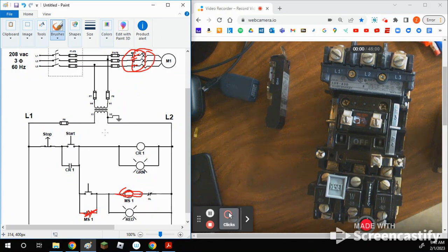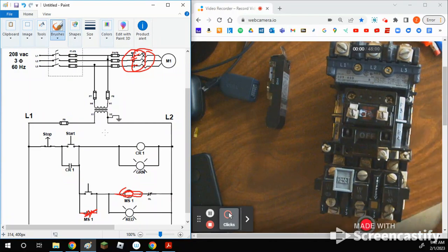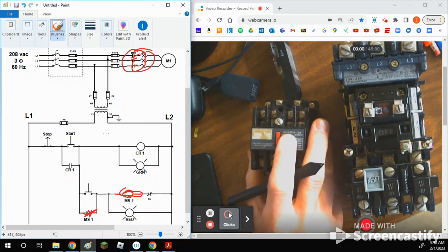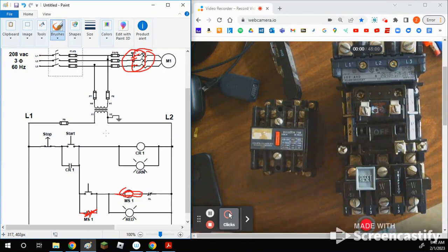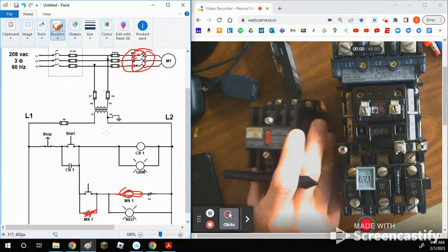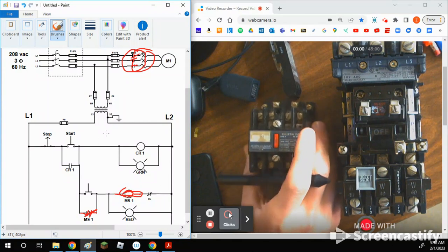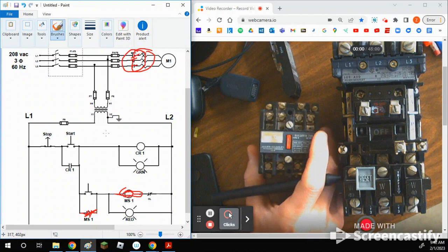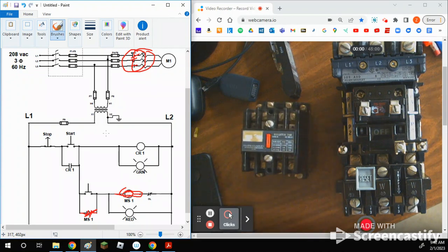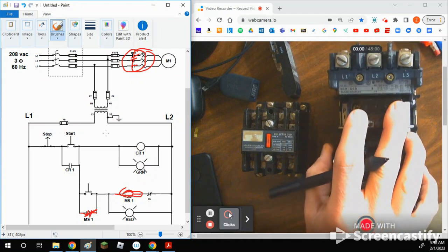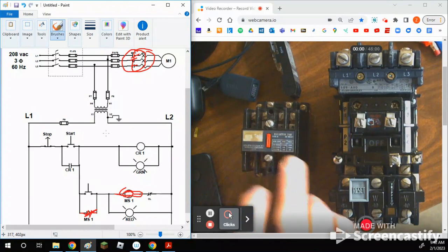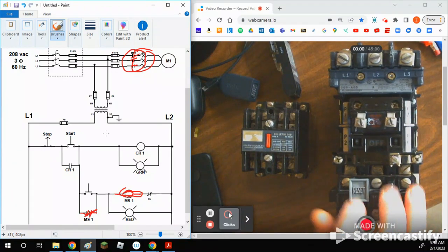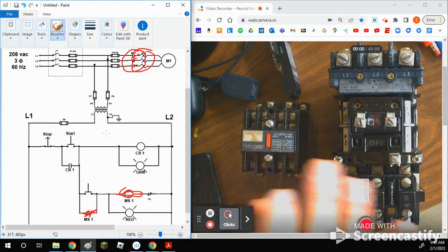So along with the motor starter, we have some other components that we're going to talk about next. Remember before I had you cross out on the first ladder diagrams, it said CR1, control relay. This is a control relay. There's all sorts of different types, and we'll cover a few different kinds in this class. But this is a pretty common, standard industry control relay. This is actually the same thing as this, but much simpler. Matter of fact, this is one of these, except it has stuff to protect the motor, right? That's the only difference between this and this.